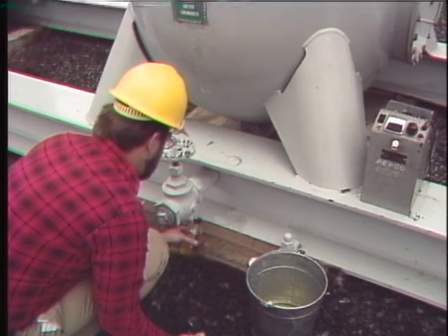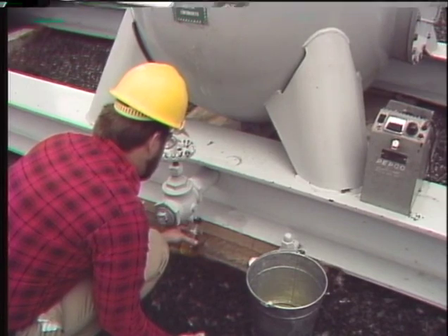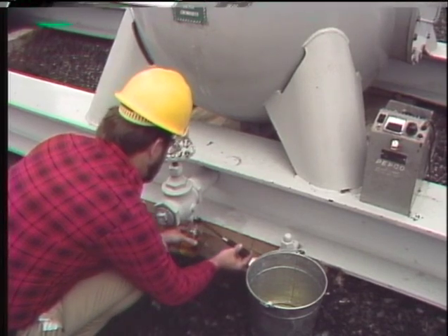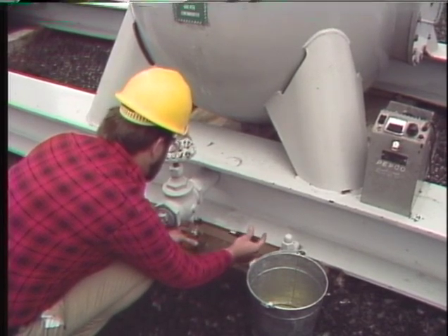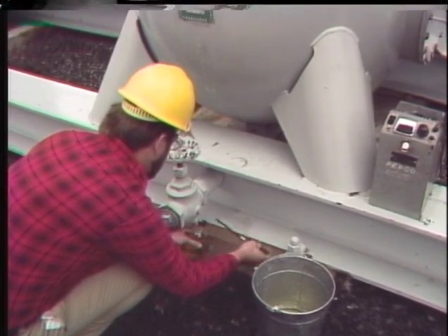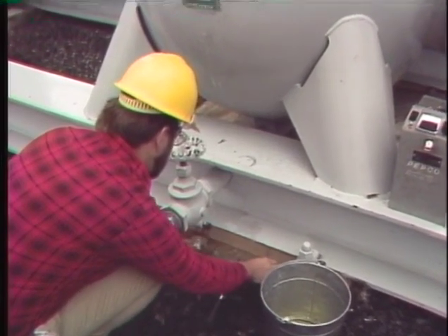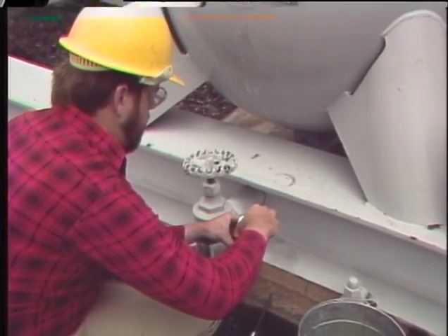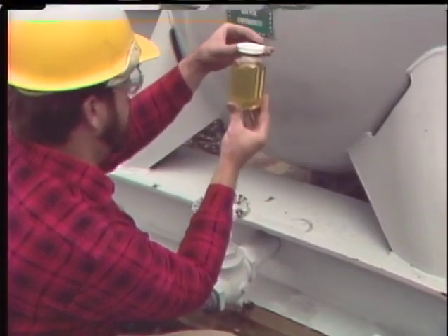To test the oil, a sample is drawn through a sampling valve at the bottom of the breaker. Several gallons are drawn off to purge the pipe and make sure the sample is from inside the breaker. If water comes out when the valve is opened, it indicates that there is a leak in the breaker that is allowing moisture into the tank. The dielectric strength of the oil will probably be very low.